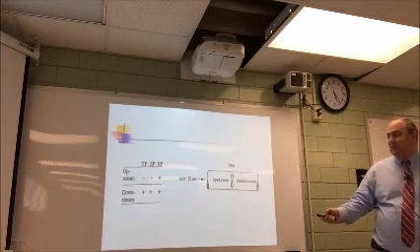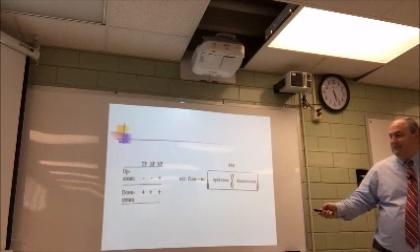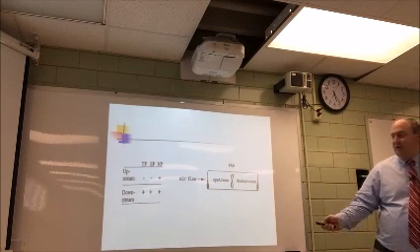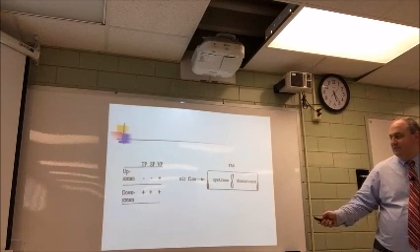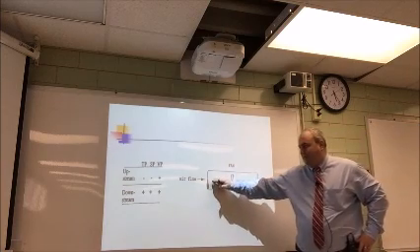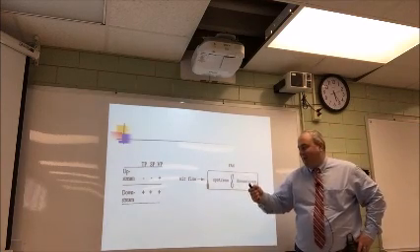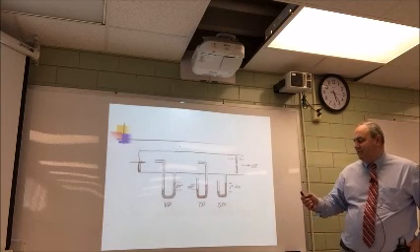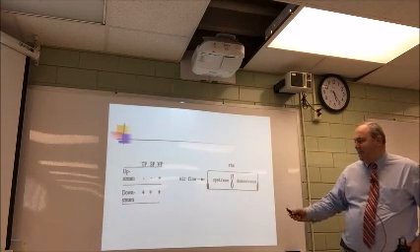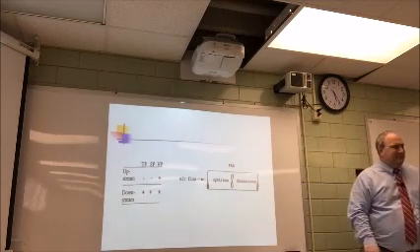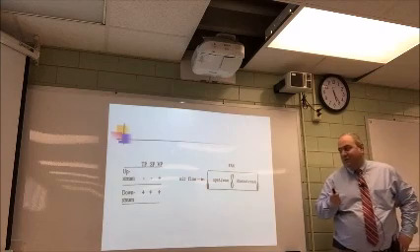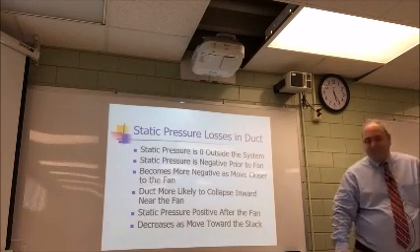Now here's what I want you to really notice. What happens here? So what is the total pressure, the static pressure, and the velocity pressure? What are the signs on them? Negative. So that's upstream. Does that make sense? Remember back to this one? How these are measuring and what's going on there. So use that. What about downstream once it gets out? All positive. There you go. So it's just a good chart to go through.